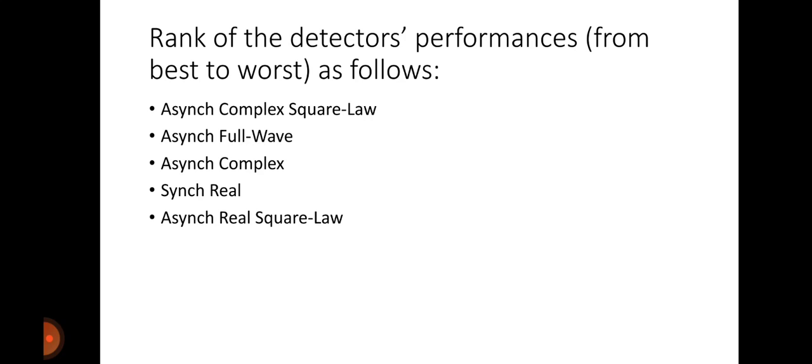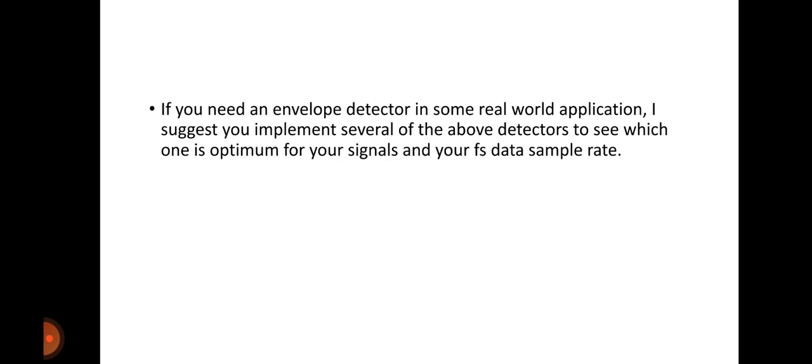Rank of the detector performance from best to worst: the asynchronous complex square law is the best one, the asynchronous full wave detector is the second best, followed by asynchronous complex, the fourth one is synchronous real, and the fifth best one is asynchronous real square law.